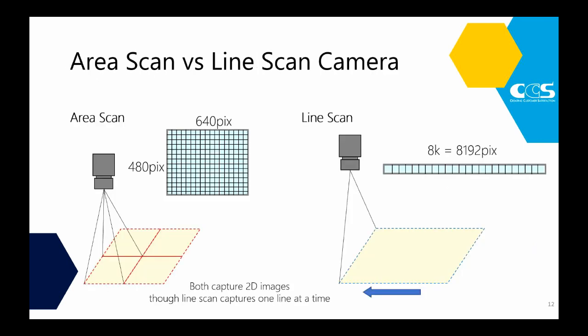So, types of cameras, there are 2 kinds. There's area scan and line scan. Area scan is great. It can be used for stationary objects and objects in motion. It captures everything in one frame, in one snapshot. It's determined by the resolution of your camera, so a kind of standard resolution is 480 by 640. 2 megapixels, 1200 by 1600 are kind of close to those numbers, and it can get larger. Up to around 25 megapixel cameras are pretty available, but that's about as high as it goes within a smaller, more affordable cost.